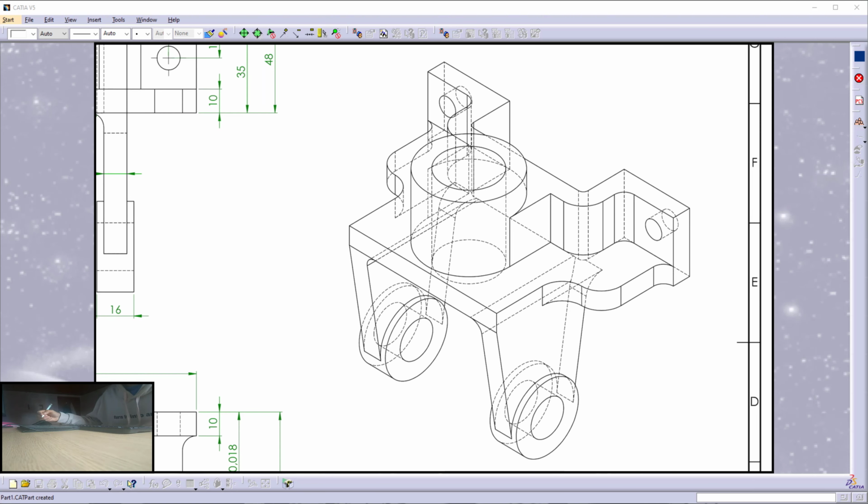Analyzing the 3D model, I'm going to start with this shape. I'm going to extrude it along this direction with this magnitude. There is one thing I should take into account to create that shape: this hole. We're going to see this later, but this hole is a through hole. That means this hole is actually like a pocket through the entire part.